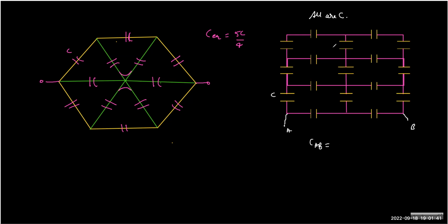So okay. What you need to understand here is that these capacitors will vanish away because they exactly lie on the line of symmetry. So no charge will distribute. The charge will go here, this will go here, so nothing is going towards this, right? Because whatever the charge is, it will be here. And therefore we have to just remove these three branches and the rest you can solve.